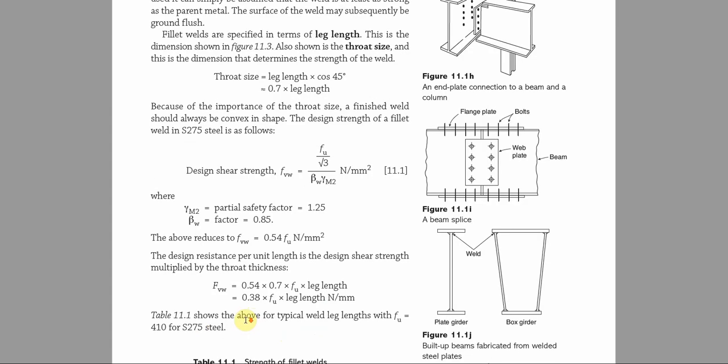By the time we substitute these values, the above equation reduces to 0.54 Fu in Newton per mm square. This is the formula for your design shear stress.